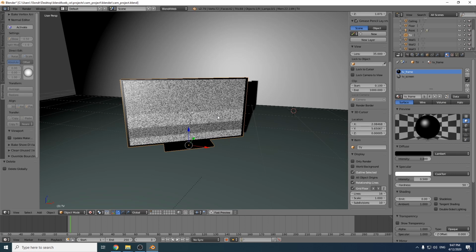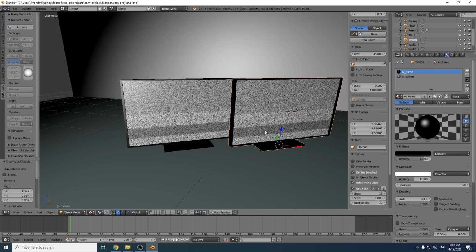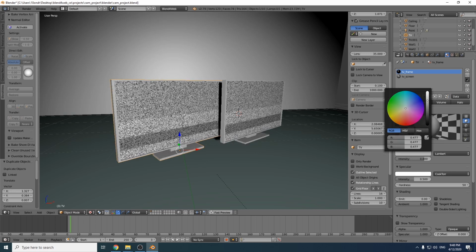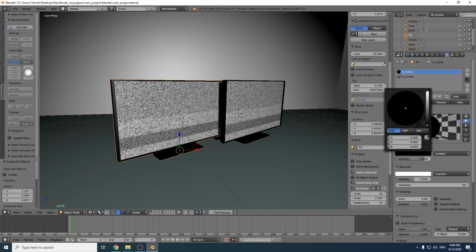So we're instead gonna hit Shift and D for duplicate. And as you can see, the material is getting duplicated as well. So now when I edit the color, oops, it will affect both models.